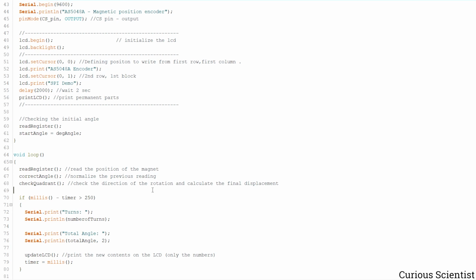So if you work with stepper motors, for example, that plus minus 0.2 degrees or something like that will not really matter anyway. And what I also have to mention is that this device is much more expensive than the AS5600. So if you don't have any special reasons to get this device, then you should stick with the AS5600, and in the worst case you have to use the I2C multiplexer, but still with the addition of that thing you will get more value for your money.